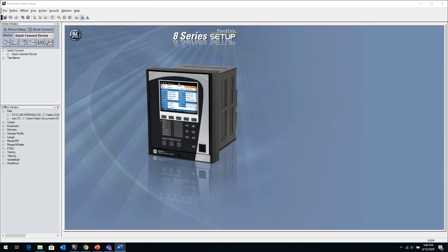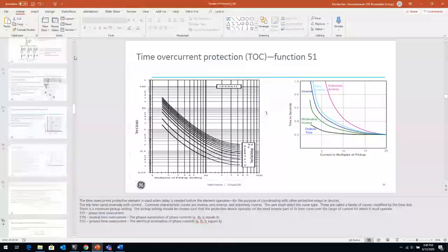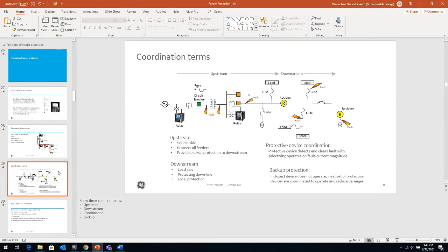Fair enough. Another participant asked about the reclosing sequence they had seen: the breaker opens, after 0.3 seconds the breaker closes, it opens again. This is for a bolted fault. Then after 3 seconds it closes, and then it will open to lockout. They were asking, what is the auto reclose sequence in North America?